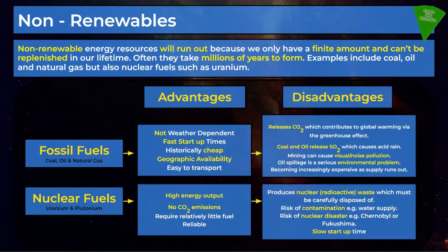Nuclear fuels, the big disadvantage of those is the risks associated with, first, there is nuclear waste in fission reactions, which needs to be carefully managed, and if it isn't managed, then there is a risk of contamination, particularly if it gets into the water supply. There is the risk of nuclear disasters, and nuclear reactors can't be turned off and on quickly. They have very slow startup times, so they're very good for maintaining a high energy output over time, but not good for peaks in demand.